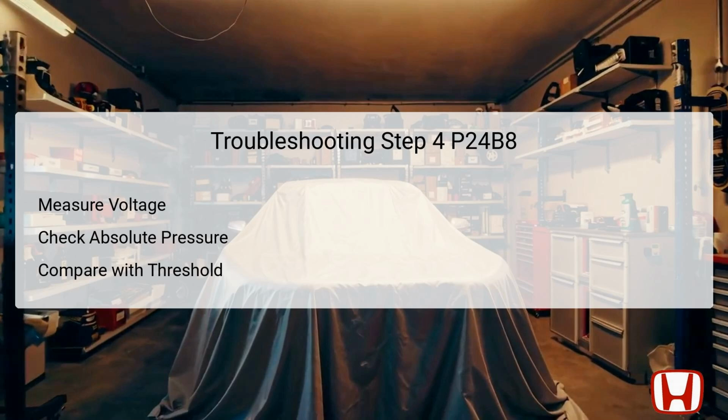In this step, we focus on checking the voltage between specific test points within the EVAP Leak Check module. With the EVAP connector disconnected, measure the voltage between test points identified at the connector's female terminals, specifically number 6 and number 8. With the vehicle in the on mode, ascertain whether the supply voltage reads around 5.0 volts. If indeed it does, this indicates that the power circuit is functional, allowing you to proceed to further diagnostics. Should the reading be inadequate, it implies a failure in the wire harness or connection, necessitating further inspection and repair in that area of the circuit.